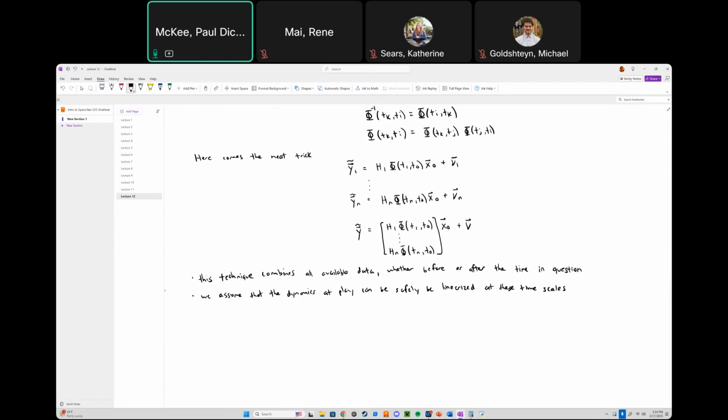All right, good stuff. So the next thing I want to talk about is a quick aside, something called observability. Those of you that have studied controls might have heard of controllability. Like, can a system be controlled to any state you want? Or can it be controlled at all? Or is it completely out of control? This is similar for estimation theory, which is kind of the twin, the other side of the coin to control theory. In estimation theory, we worry about observability. Is it possible to reconstruct the state from these measurements? And the answer is not always.